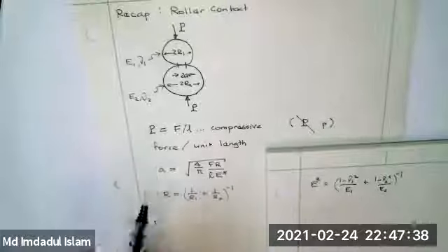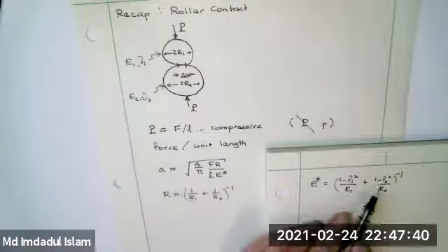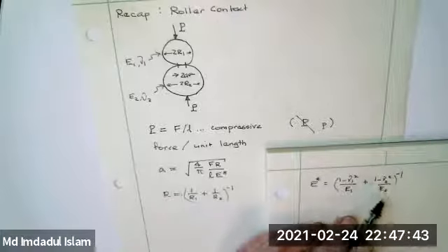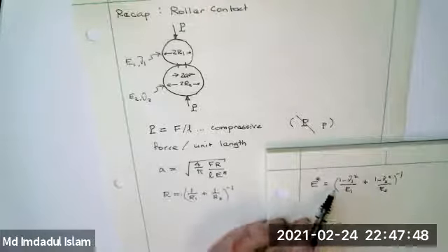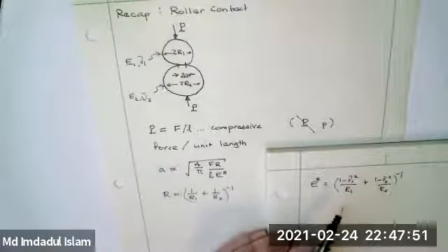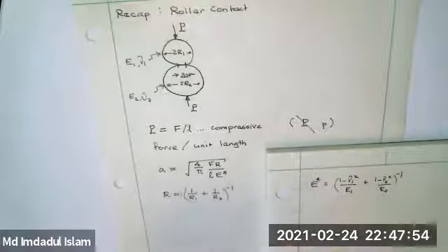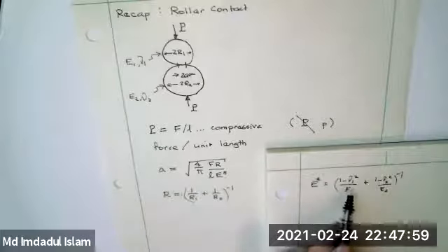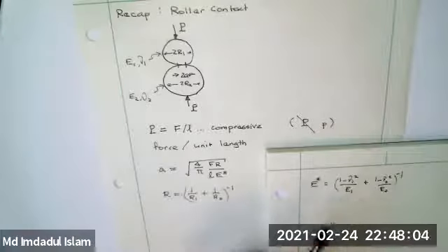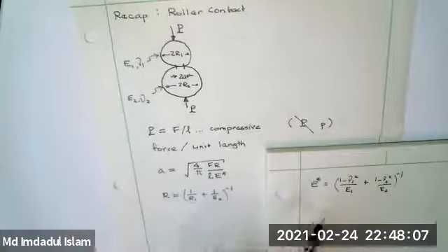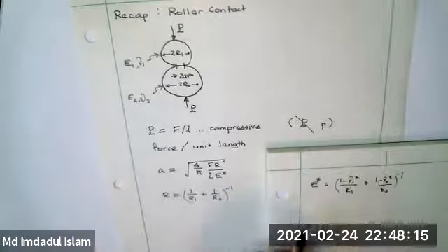So if E2 was infinite, what's that mean in engineering? A factor of 10 or maybe 100 times bigger. You throw this away, you flip this over, you get E1 over 1 minus nu1 squared. When you divide by 1 minus nu1 squared, you make it slightly stiffer. That's because of the Poisson's ratio effect of pushing it around. If E1 equals E2, you'd just get a 2. And so this modulus would become E1 over 2 times 1 minus nu1 squared. That's very common. You often push things with the same modulus here. And so now, because they're both compliant, the effect of E has gone down. Then the pressure,